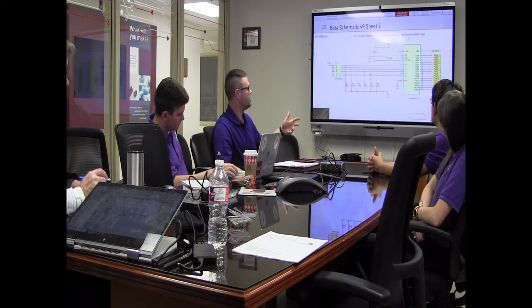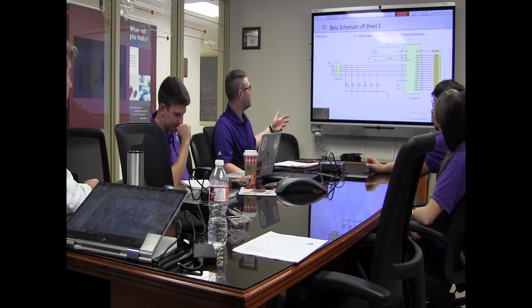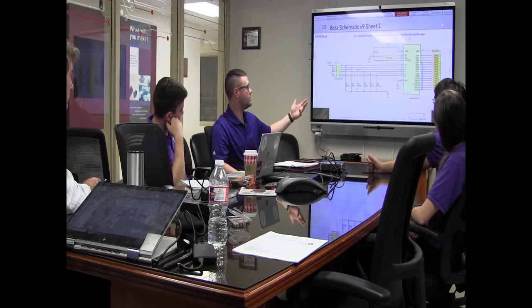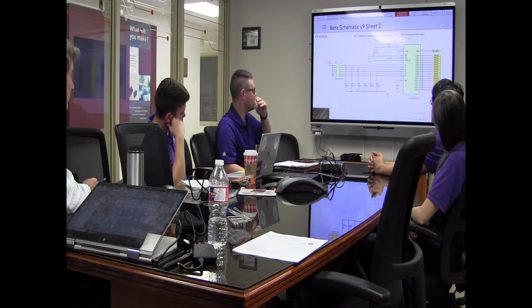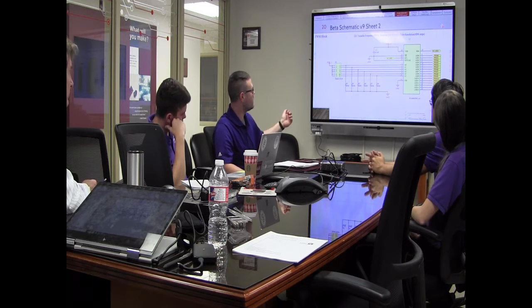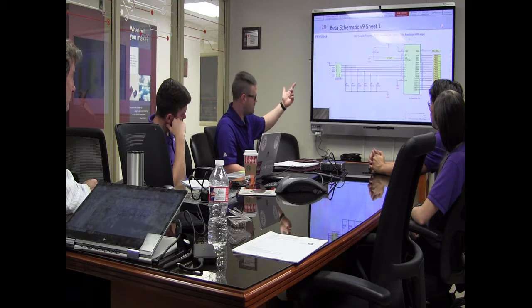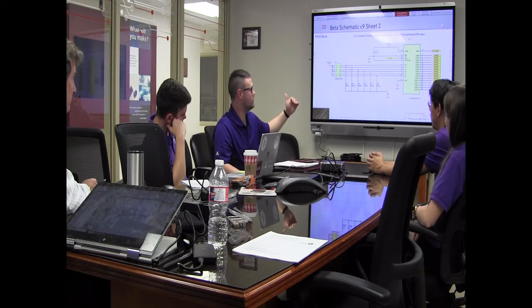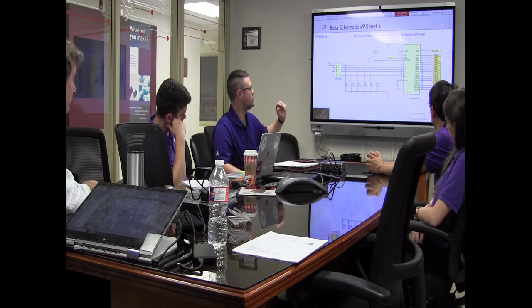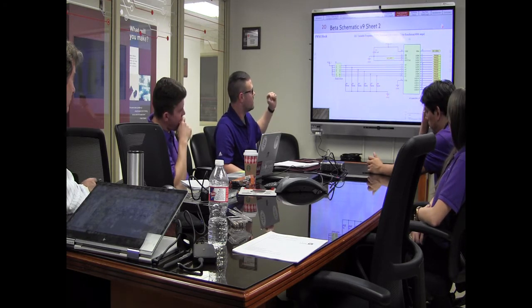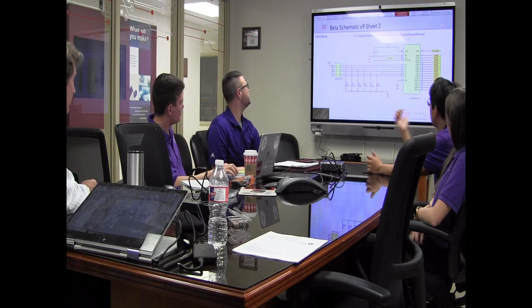So that's sheet 1. Keep going. Sheet 2. Here's that PCA 9685. It's our PWM generator. We can also select the I2C address, 6 bits of it. The 7th bit is fixed. And we're feeding that 5 volts directly from one of our voltage regulators. A little bit of decoupling happening, but not much, because they're super close together. And I2C coming in from our CC3200. Go to the next one.